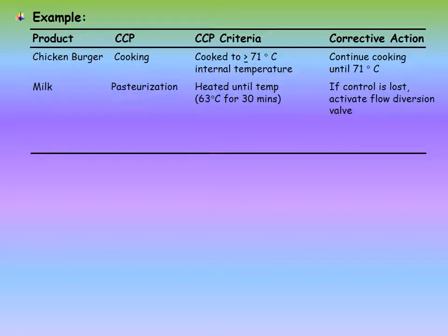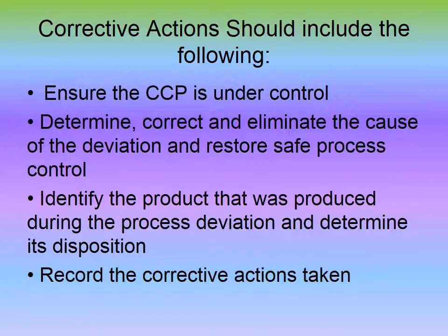And you can see another example. For example, CCP pasteurization, and the corrective action for that particular CCP. For example, if control is lost, we can activate the flow diversion valve. So we can go to the corrective action.